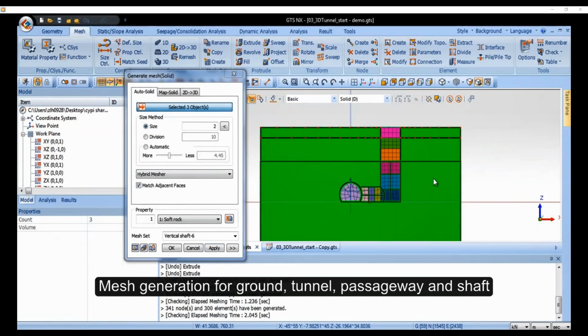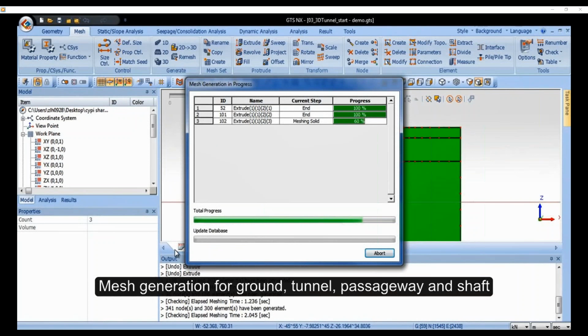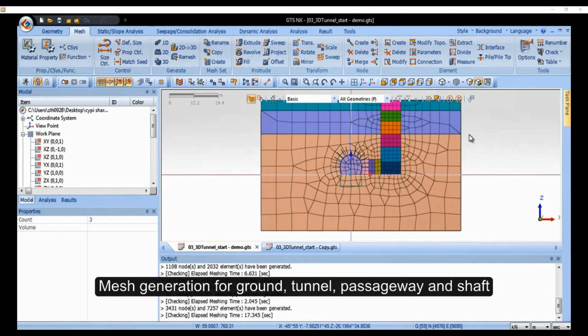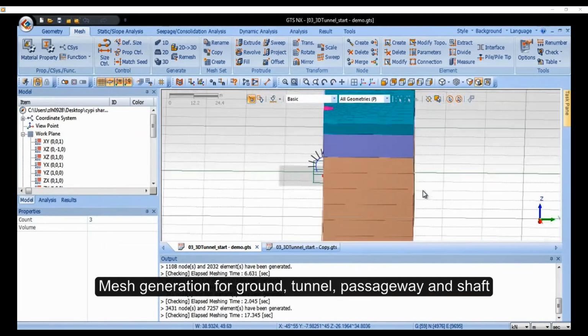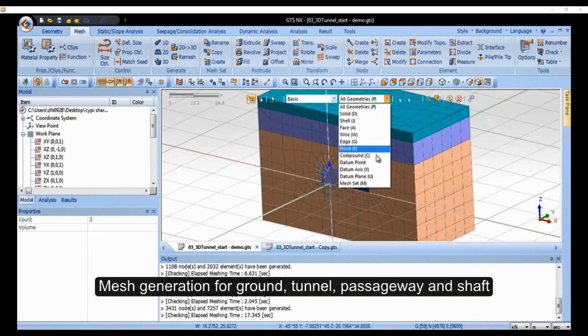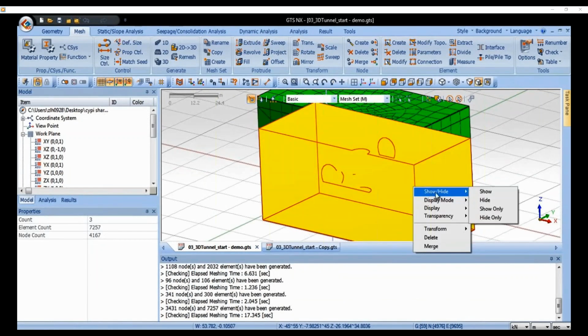And now I'll start meshing the layers. One can mesh one by one and assign the appropriate material, or you can always mesh them all together and then go back and modify the material assigned to them in the workstream. So here we'll just give them all a uniform size and mesh them in what we call mesh in the same step or parallel. So we have essentially finished meshing our model.